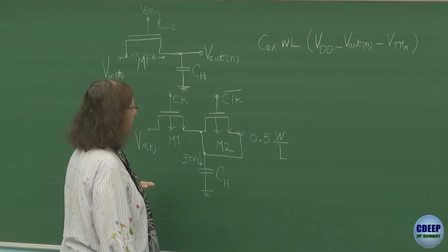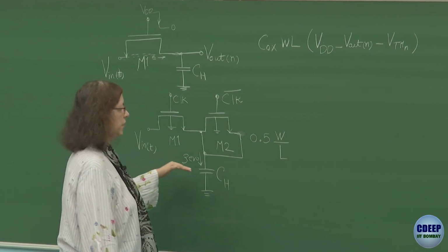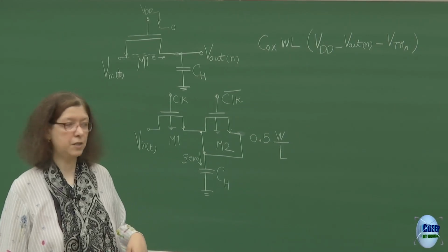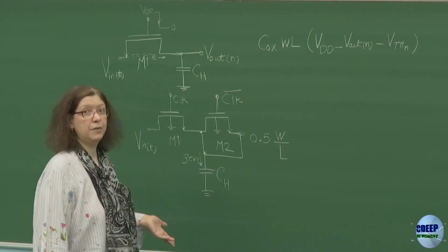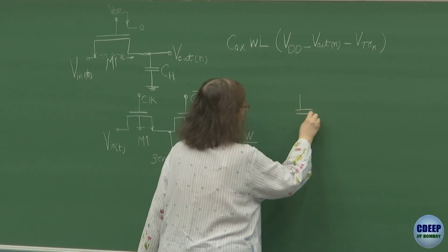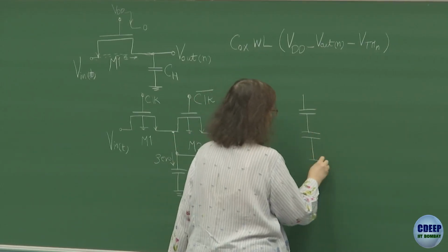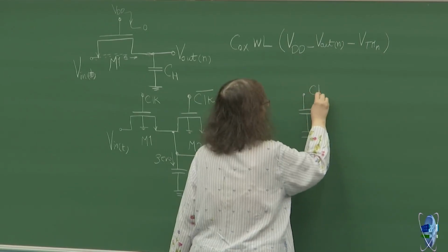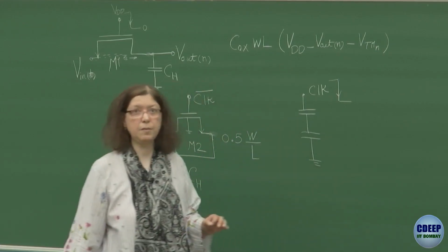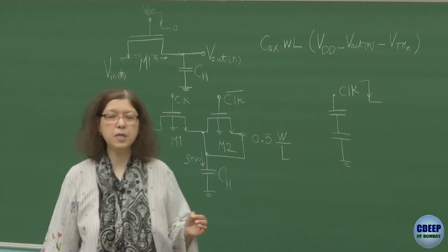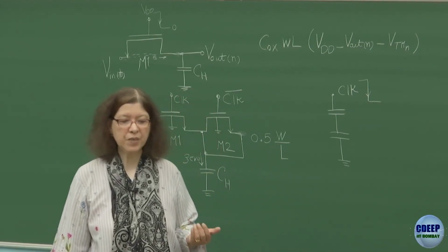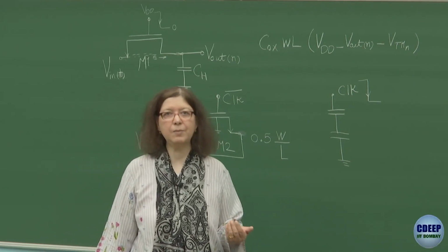Now, if we look at this way, which is very straightforward, considering partial at least compensation or nullification of the charge injection, we want to see now what will happen for the clock feed-through. So therefore, we draw the equivalent circuit for the sharp edges to get a better idea about clock feed-through. This is clock, which is going from high to low, and clock feed-through is extremely important when the switch turns off, because when the switch is on, even when it turns on, we have the clock feed-through, but the effect will get compensated, only it may add to the delay.